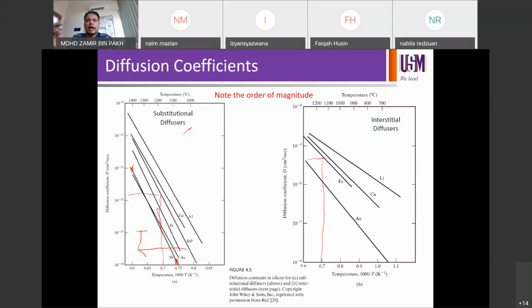But if you have cross contamination, for example, your chamber has contamination, with all this unwanted metal inside the chamber, then you run your diffusion at high temperatures. What's going to happen is instead of only diffusing the phosphorus or the boron at that particular temperature, you will also diffuse the unwanted metals into the lattice. As a result, this will lead to recombination or trap centers that we discussed in 386 last time.